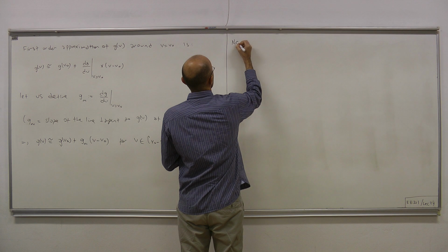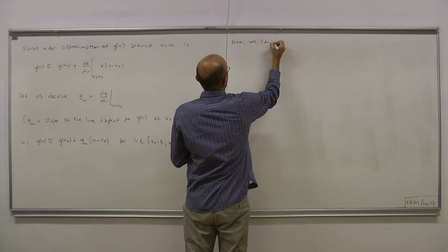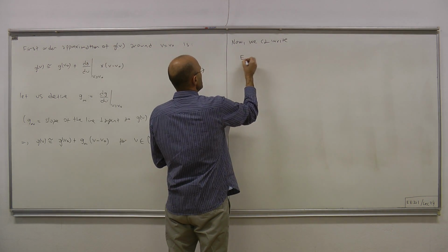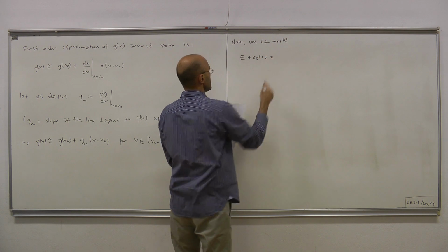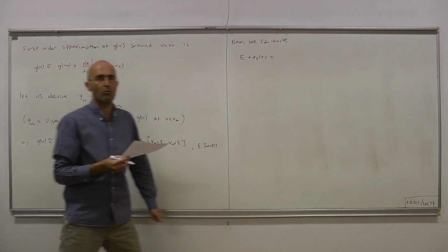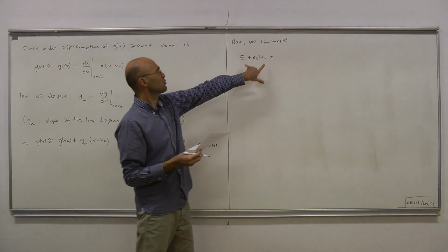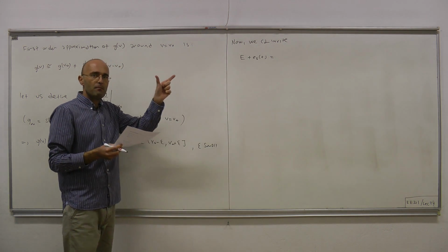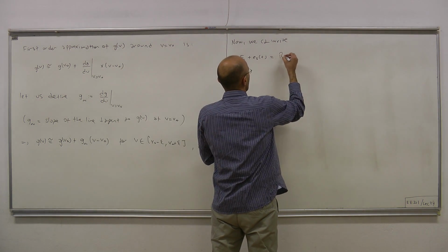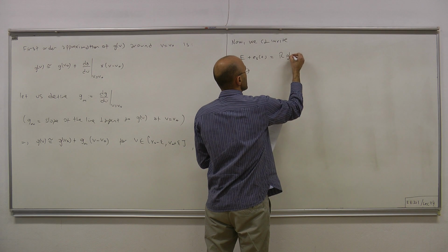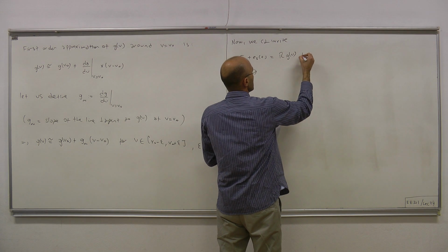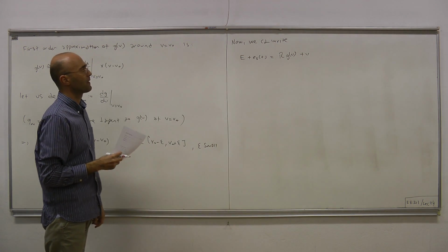Okay, now we can proceed as follows. What we have is E plus ES of t. So this is the overall voltage provided by the source, both DC component and AC component active. Now this voltage equals voltage drop across the linear resistor plus voltage drop across the nonlinear resistor, namely R times I, the current, and current is a function of voltage, G of V, plus the voltage of the nonlinear resistor.